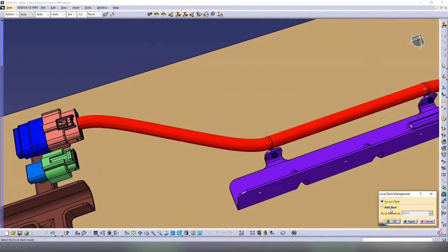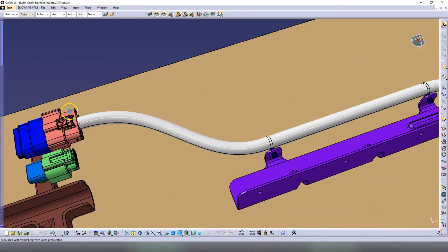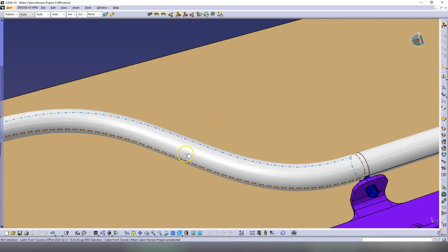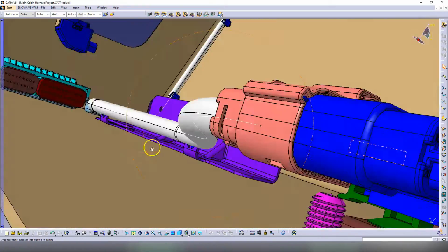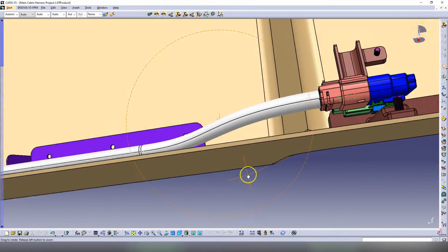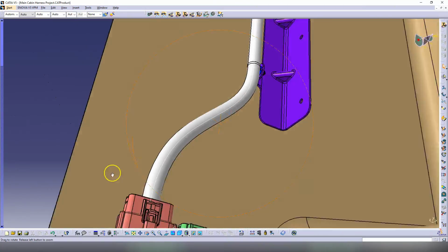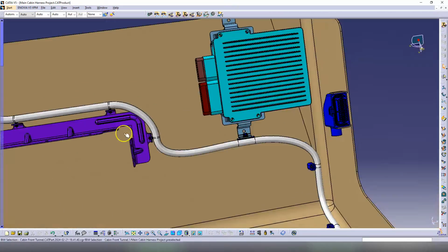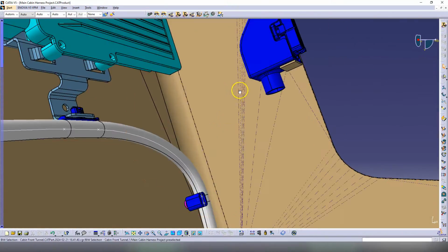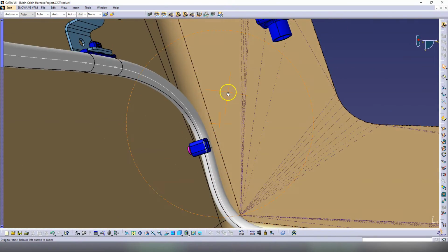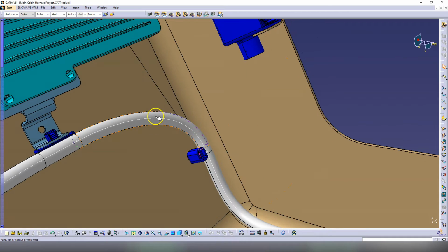And in here, again, this is a long piece of harness from this retainer to this connector. So you need to be careful what we have around here. You need to check on the 3D models that it doesn't vibrate onto something. Okay. So from here we decide where we go into this connector here.